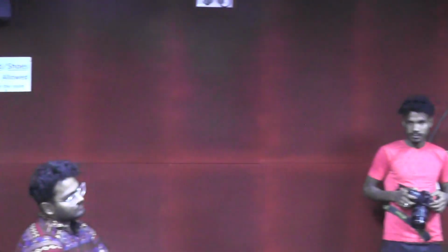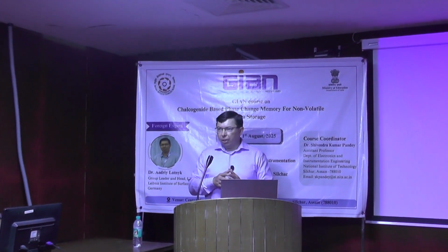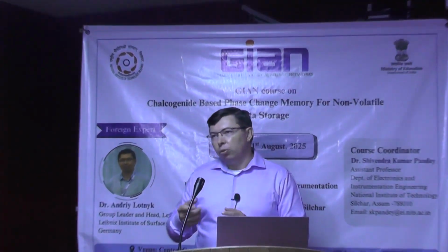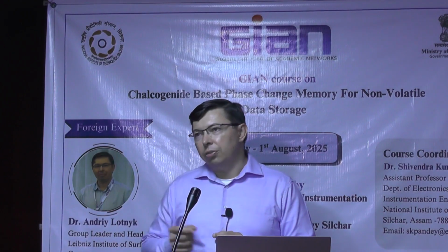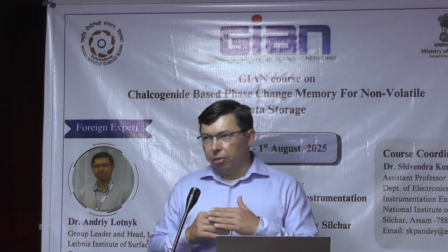What do you mean? The additional protective layer we need, is that what I was saying? Yeah, but it's for optical properties. If you want to measure optical properties and you want to overcome this oxide layer formation, you should cover it by another oxide layer which is optically transparent in your wavelength range. But if you want to use electrical switching, of course you don't need to deposit the protective layer.